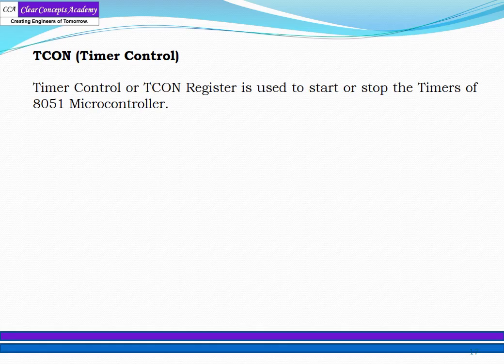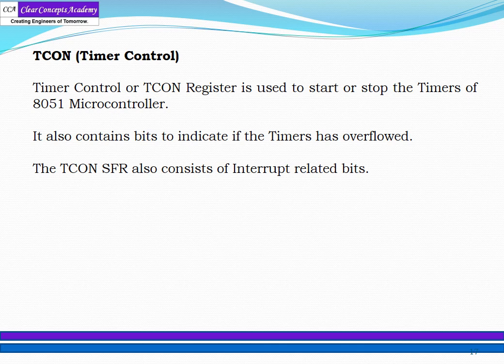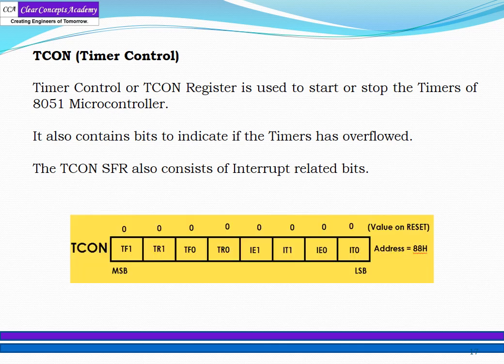The timer control, or TCON, register is used to start or stop the timer of the 8051 microcontroller. It also contains bits to indicate if the timer has overflowed. The TCON special function register also contains the interrupt related bits.